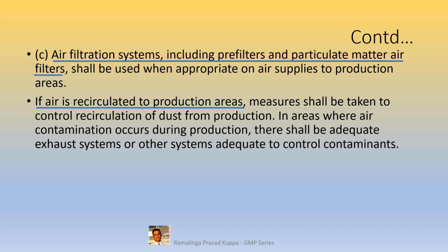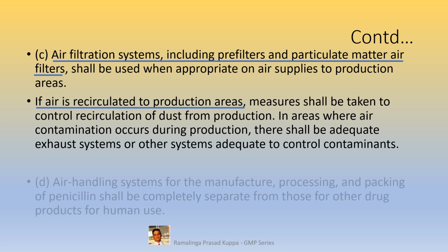So, venting out of such cooled air into outside atmosphere is not economical to operate. In such situations, the cooled air is recirculated. Recirculation is done by filtration of the outlet air through various filters and introduced into the inlet stream. Since the same air is recirculated, oxygen content in the recirculated air may not be adequate. 10% of fresh air is added into the system to compensate. Fresh air is introduced at the cooling systems.